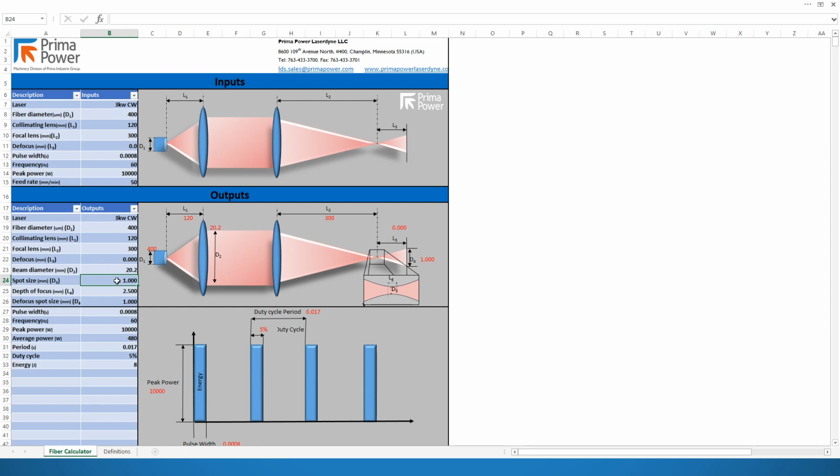In a typical automotive application, we could achieve feed rates of around 4 to 5 meters per minute, utilizing the maximum power of this laser. In today's demo, we will instead select pulse so that we can achieve maximum penetration while still inputting minimal heat into the material. Pulse width will be based off of experience with a similar application. I will begin trials at 8 milliseconds or 0.008 seconds.